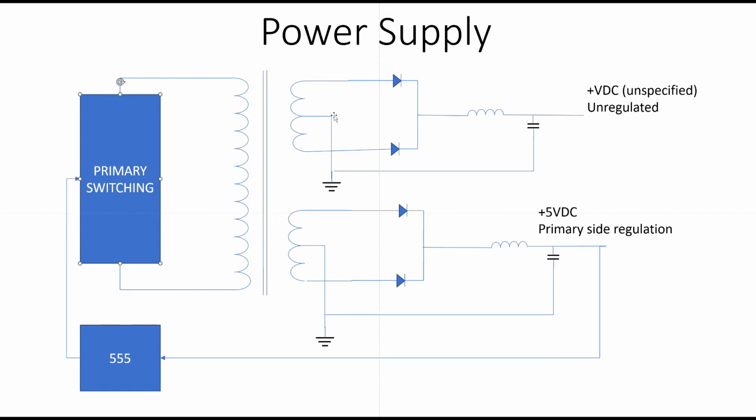If we translate that across onto the higher voltage outputs, which we're saying nominally are about 15 volts, then we've got exactly the same diagram. We've just got more coils in the transformer, so we get a higher voltage out into these diodes, through the same sort of choke and into the same sort of capacitor. It's not really surprising, since there's no bleed resistor or anything like that on here, that this voltage continues just to rise, because there's nothing taking the energy out of this capacitor. So it will continue to go up until it reaches whatever the maximum output is from this transformer. It's just getting these little blips of high energy, storing them, then getting the next blip, storing it, next blip, storing it. And so the voltage there just rises up bit by bit.